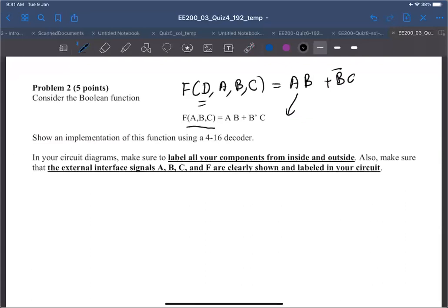Okay, so we have dash 1 1 dash, right? Yeah, because this is not mentioned here, and this is not mentioned. Okay, so we have dash 1 1 dash. This can be, we have 4 values here, basically. So this is going to be 0 1 1 0, 0 1 1 1, 1 1 1 0, and 1 1 1 1. Okay, so these are the minterms covering this product term.